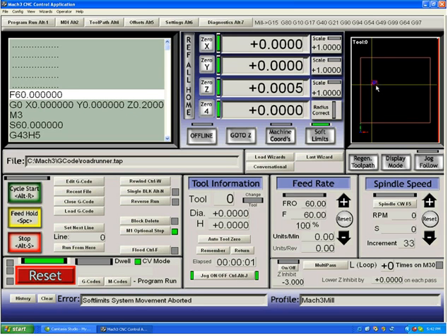But let's say that you always wanted to cut this Roadrunner at 50-50 on your table because you have maybe a jig here which holds your board securely. To do that would be pretty easy. All we'd have to do is home our system so that we know that we're accurately at home. And again, I'm going to cheat this system by telling it, there we've hit our switch, and now the X has hit its switch, and now everything is zeroed.